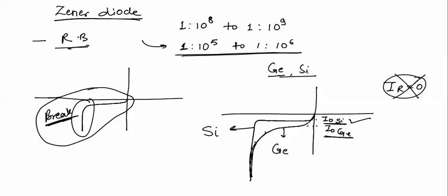And another one is that in the germanium diode, this is the current axis and this is the voltage axis. The increase in current in this particular part is gradual. In reverse bias, in this region, the diode is not operating; only a reverse saturation current flows through the diode. Now the current is increasing, which means the diode is entering breakdown. This breakdown we can see is gradual. But if we take a silicon diode, then in the characteristics I have shown that this breakdown is sudden.